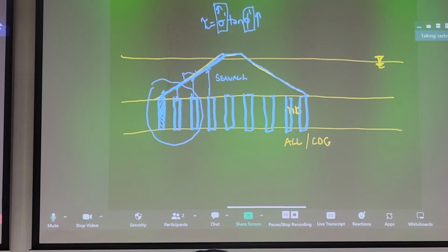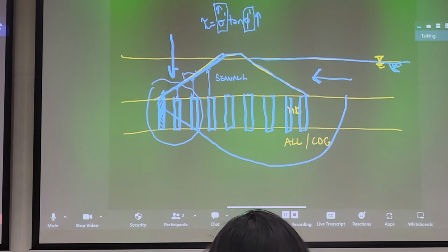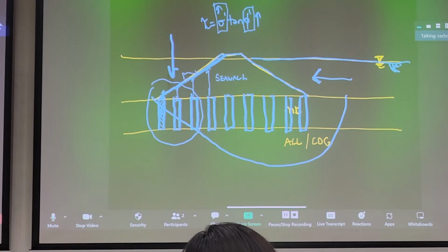Now, why is that an issue? Well, when seawalls fail, they don't fail vertically down, because what kind of load do you have? Well, if you fill this with fill, you actually have earth pressure, pushing this way, right? A typical failure mechanism might look something like this: it could cut through the seawall, and your seawall can maybe settle and slump. This happens, reclamations fail, seawalls fail.